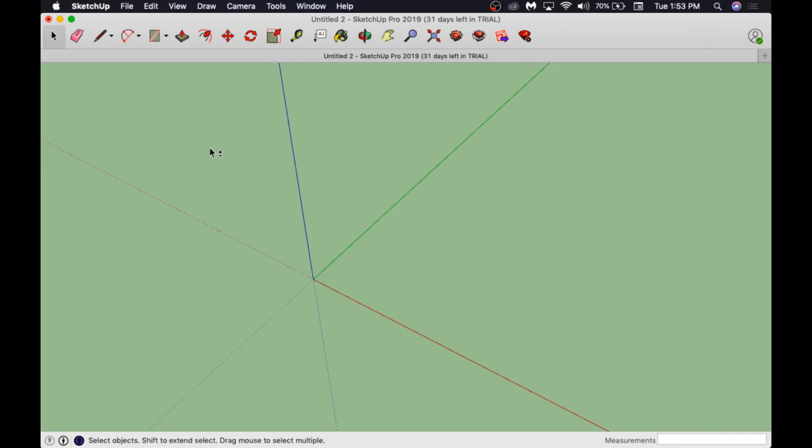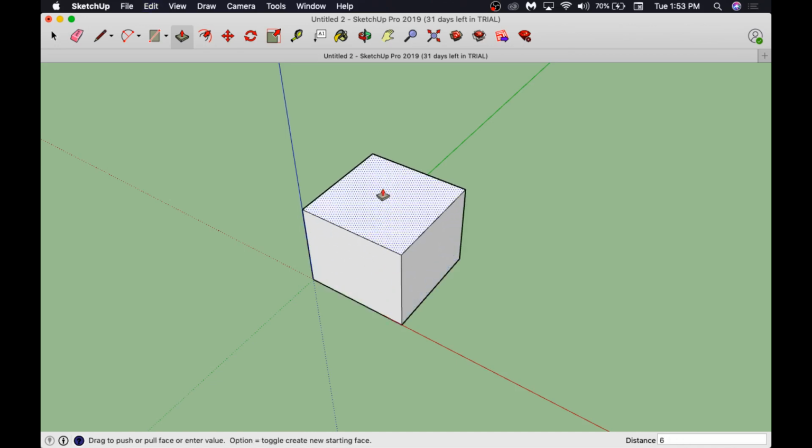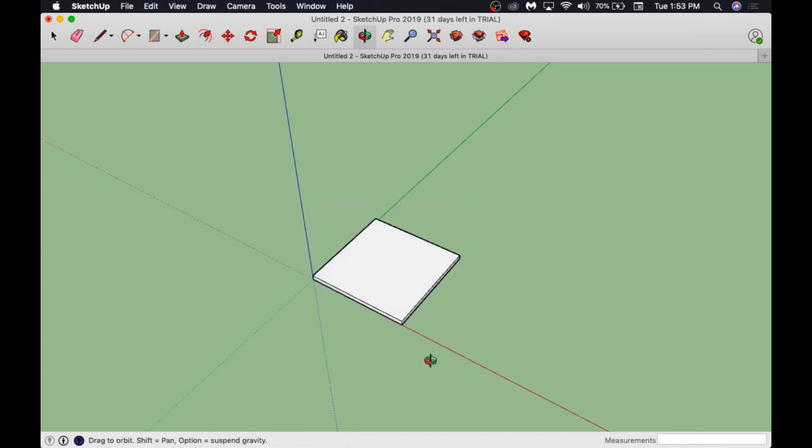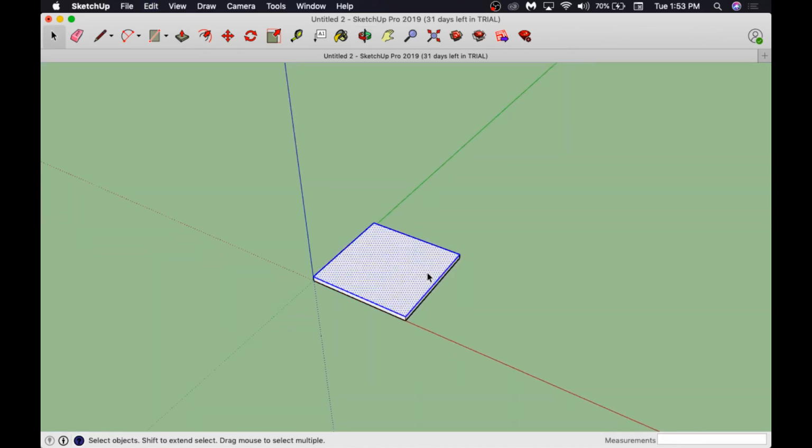All right. So first things first, we just use the box tool. We're going to put in the value 10 foot, comma 10 foot. Enter. That gives us that. Then we're going to use the push pull operation right here. 6 inches, like that. So there you go. That's our push pull tool, object set. Triple click on it, Control G to group, always.